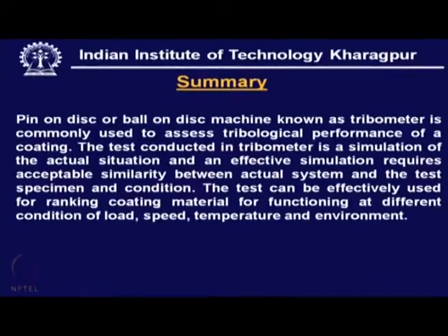So, this way we can look into the various aspects of tribometry, that means the measurement, the science and engineering of measuring the coefficient of friction, then the resistance to wear of the coating. For a particular coating, the behavior can vary depending upon the structure of the coating, the crystallographic orientation of the coating, and sometimes the coating is also sensitive to humidity.